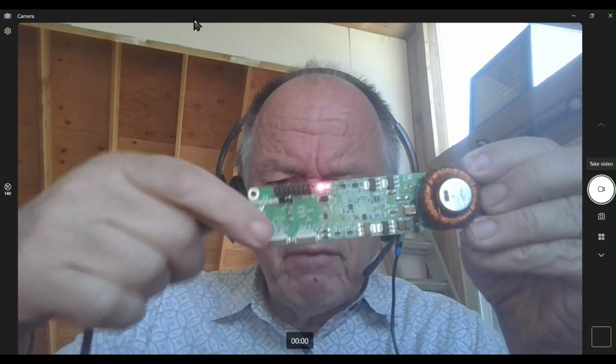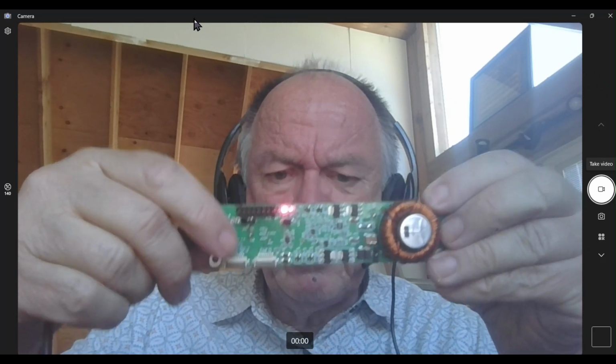Hello, in this video I'm going to show you how to install code on an OASIS platform such as the EM-60, and there are two methods of doing that. The first method is via the USB port here. It does require that the bootloader is installed on the EM-60, which is the case as it comes from the factory. Sometimes as you're using your development environment, you may just wipe out the bootloader as part of that, and that's okay. I'll show you how to reinstall it.